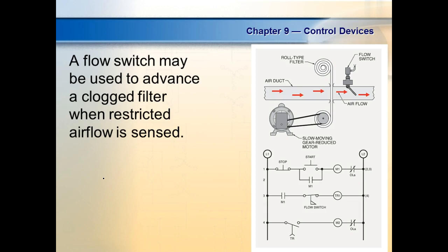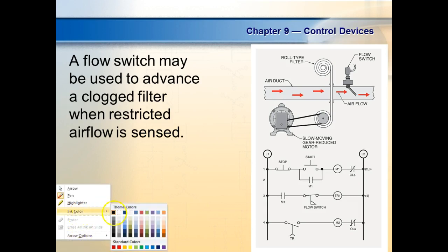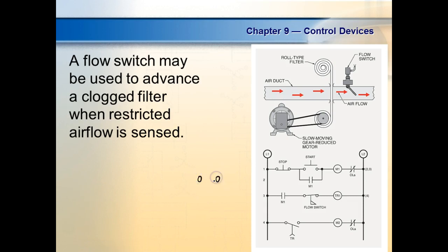The washing machines use on delay timers. So you start it up, and after a while they'll turn on water, right? You understand? And then after a while they'll do what? Do that. So those are all on delay timers. So this was an on delay timer. An off delay timer, we're going to teach timers later on, the different types. But an off delay timer would look like this. The arrow points away from the switch. An on delay timer, the arrow points toward the switch.